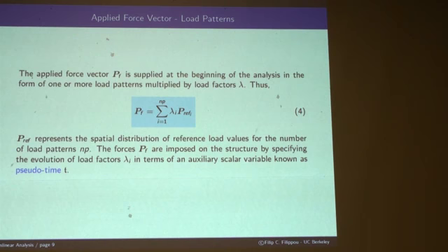So to describe the incrementation or the change of the load factor, I need to define that in terms of an independent scalar variable. You can call that scalar variable anything you want. The typical term used in nonlinear analysis is pseudo time, because it's not real time, right? Remember, we said that the forces change very slowly with time, therefore they are not dependent. All right.